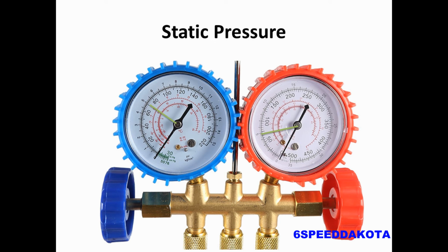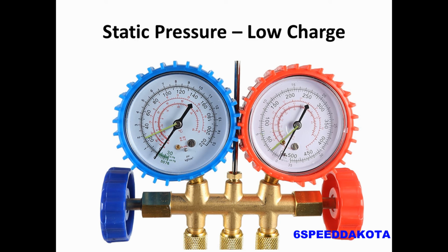So ignore the black needles and just look at the ones I've drawn on there. I know it's kind of cheesy. So if our system's low, again, at 70-degree ambient temperature, you're going to see the gauges are quite a bit below what it should be. So we know that our system charge is low, so we have to start by looking for a leak.